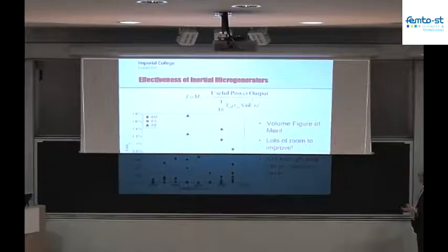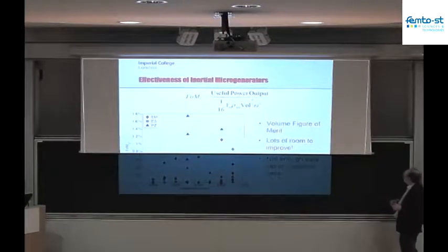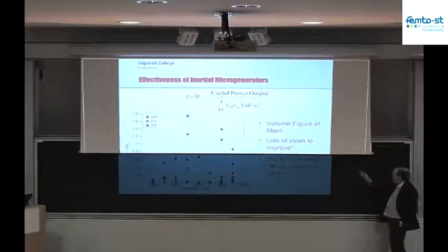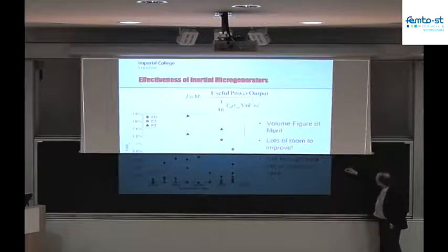So you remember, I'm sure, Fourier analysis, and you remember how to build a square wave from a set of sine waves. If I want to turn this sine wave into a square wave, I start adding in third harmonic, fifth harmonic, seventh harmonic, etc. And the strategy, of course, is always to try and add in the next harmonic that makes this wave look a bit more square. And to make this look a bit more square, I need to add in a third harmonic which increases the gradient at the edges here and pulls the top down a bit.